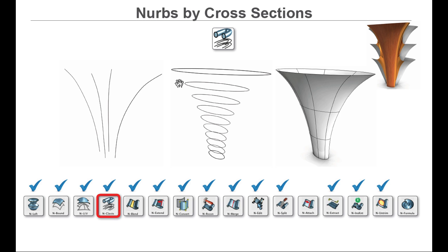And this shape was derived by just creating some silhouette lines, which represent the overall silhouette profile. And then what this tool does is it cuts the cross sections for you. So instead of you creating cross sections like we did at the very first tower example and we lofted it, we let the program create the cross sections for us. And so all we need is some guidelines for it. And it also has a create surface option, so it'll also generate a NURBS surface if we want also.